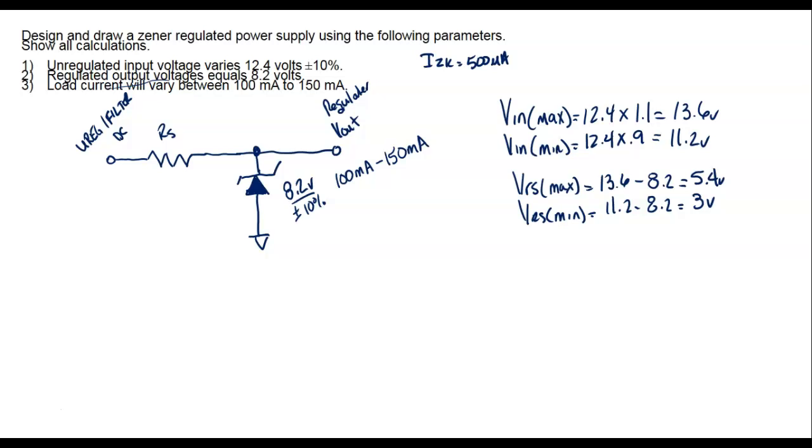If the load current goes up, then the Zener current's got to go down. Y'all understand that? So the Zener is literally changing its dynamic resistance. This is the big change between solid state devices and resistors. We can set up these things so they dynamically change their opposition, and bipolar transistors are exactly the same.